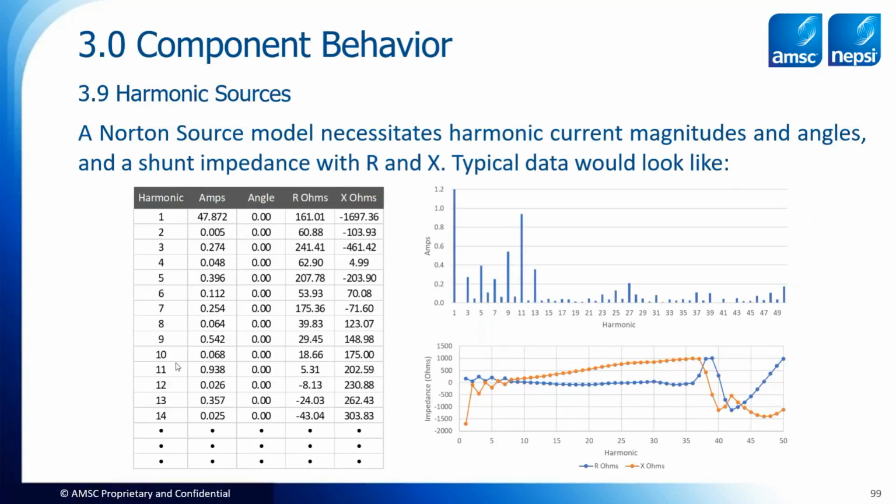They move further and further away from the center band at non-integer frequencies. So you need to include that in your simulation as well if you have devices with cycloconverters. So this is not just an integer number. Here in this example it is, but you could have these being 1 to 1.2 to 1.3 to 1.4, everything as it's stepping through the harmonic spectrum.